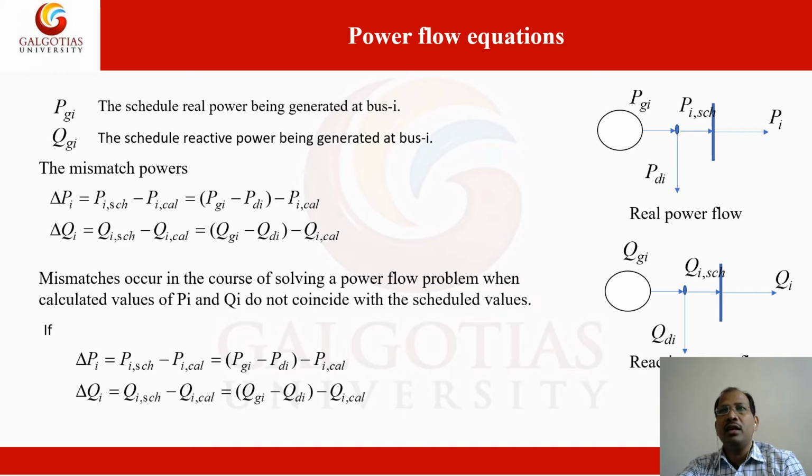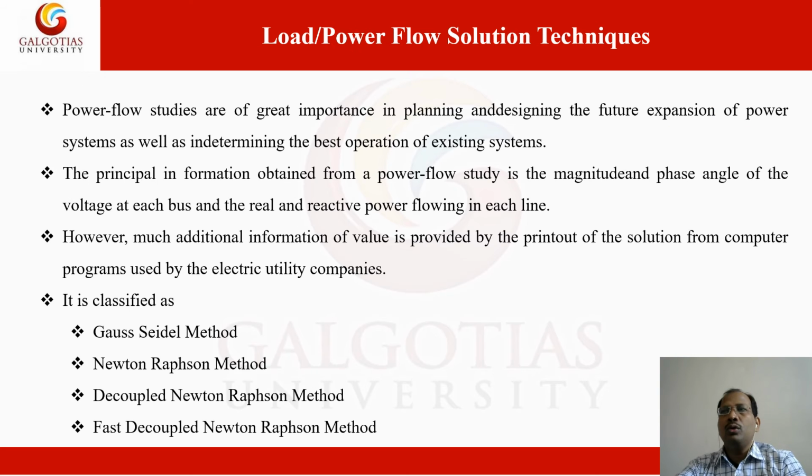If the system has a mismatch, then we have to apply the load flow equations, or we solve the load flow solutions using the Newton-Raphson load flow and some advanced techniques. As we know, power flow studies are implemented for a particular network when we want to plan and design the future extension of the power system, or we want to know the power system's current conditions. So we have to determine the base operations of the existing systems.